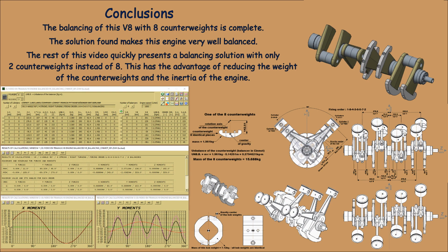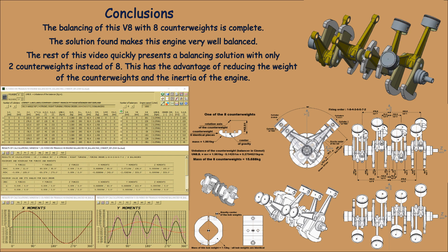The balancing of this V8 with 8 counterweights is complete. The solution found makes this engine very well balanced. The rest of this video quickly presents a balancing solution with only 2 counterweights instead of 8. This has the advantage of reducing the weight of the counterweights and the inertia of the engine. Let's watch it.